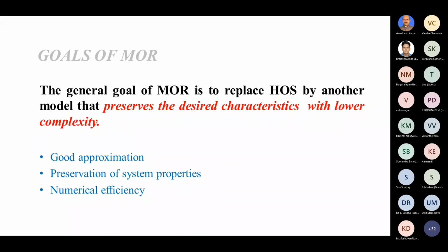Say, for example, we will later see that a time domain technique known as the Krylov subspace technique is an implicit Padé approximation. If we go for explicit Padé approximation, it becomes a frequency domain technique. So people have themselves classified in different ways. We'll do it based on our own classification. We'll be doing projection based and truncation based techniques, right?